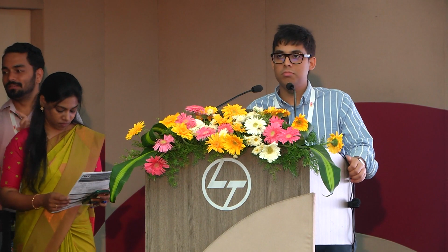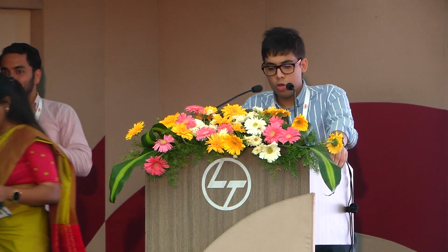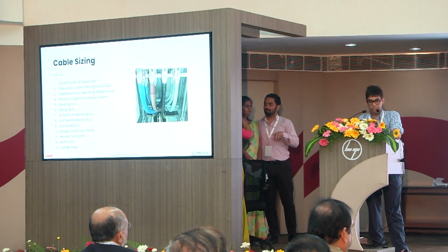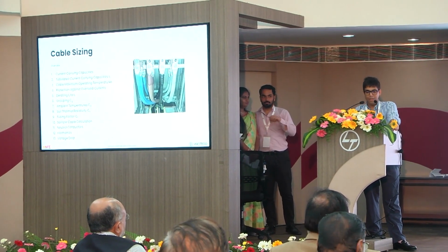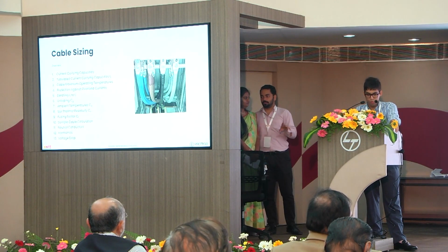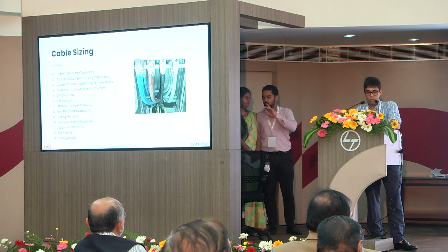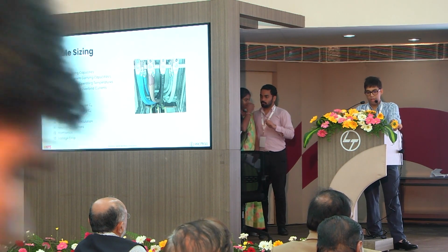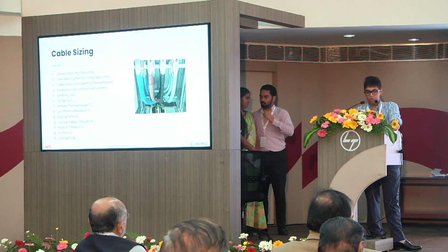Okay, so let's begin. For cable sizing, there are 13 basic things that I want to cover. One is the current carrying capacities, how these are achieved. Then you have tabulated current carrying capacities, which is what the manufacturer and the standard will give you, and these are usually based on your cable maximum operating temperatures. Some loads, as you know, require protection against overloads, some don't, most do.